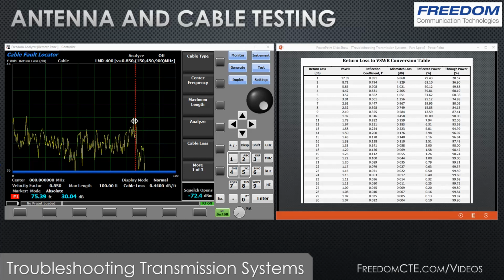This is the result of a sweep with the 50 ohm termination on the end of the cable. You can see a much less pronounced return loss spike here. It's actually no longer the peak, and you can see the value is right at 30 dB. If we look at our chart, 30 dB is 1.07 to 1 VSWR. Excellent. Very good match. Obviously not perfect, but a very, very close match. We're only reflecting approximately 1/10 of 1% of the power.